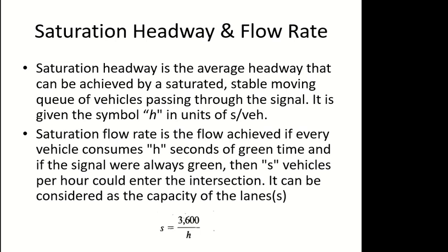If headway is minimum, then the flow rate is maximum, because they are inverse, right? And then you can see here 3600. What is this 3600? It is the conversion factor. The headway will be in seconds, obviously. Minimum means it's a very low value in time, so seconds. And then the flow rate has to be in per hour, right? So that's why you see 3600 here.